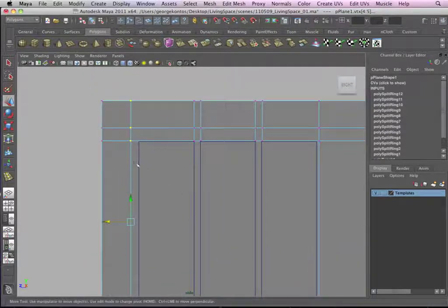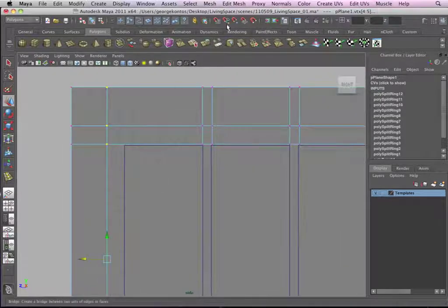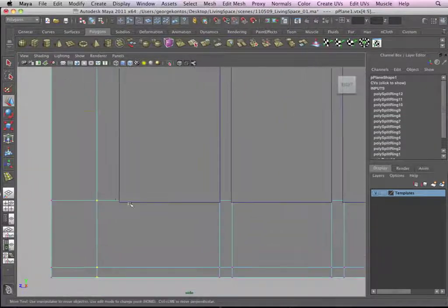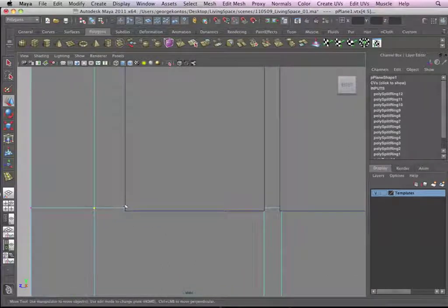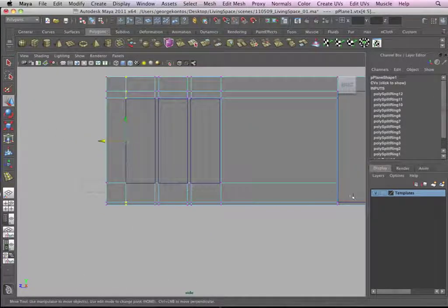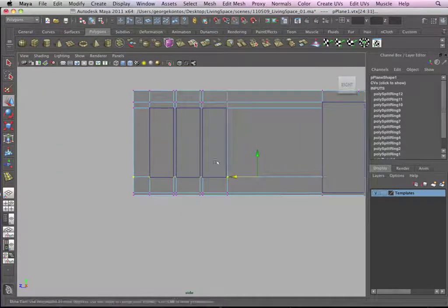Now if you don't have to be close, you just have to activate the Z and then turn on the snap to point, and now you only need to go to the destination area, which is this point here. Any of these points, either the point up here or the vertex down there, will do. So if you hold down the middle mouse button and draw around this point, it will snap. The same goes for this edge, you need to get the whole edge, so all the vertices.